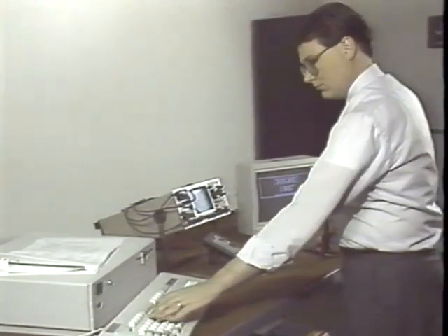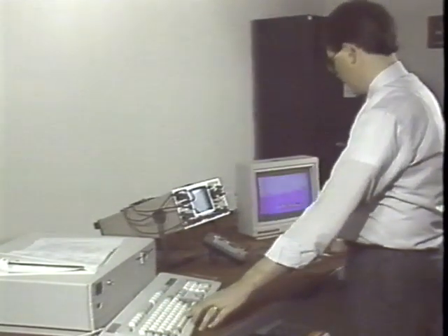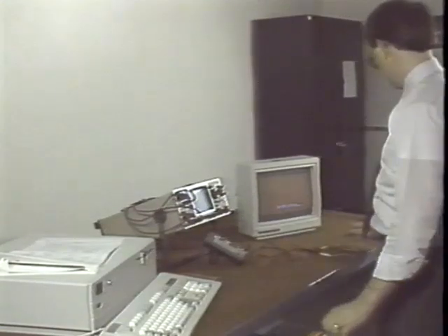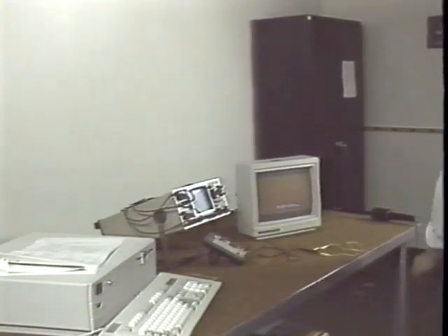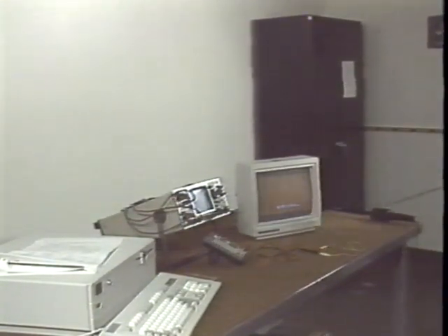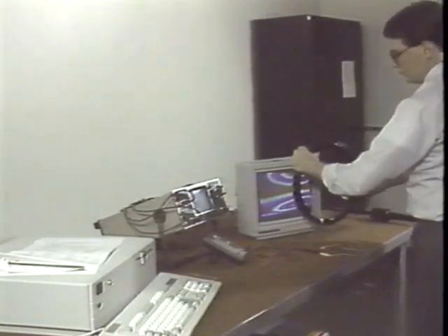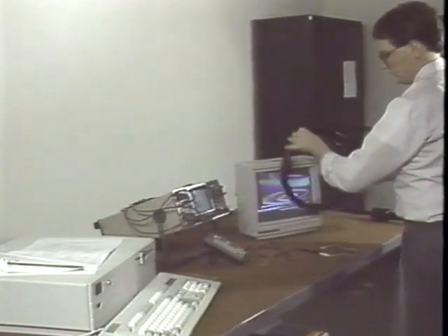To manually degauss a monitor, first turn it on. Then plug in the degaussing coil and turn it on while standing about 6 feet away from the monitor. As you walk towards the unit, circle the coil in front of the tube. The screen will appear to run and change color due to the effects of the coil.